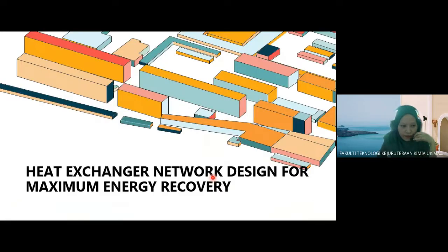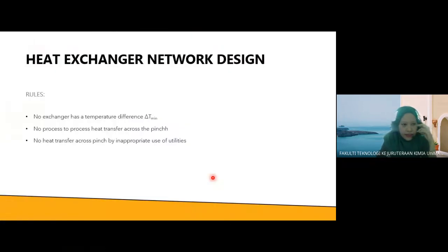Okay, now heat exchanger network design for maximum energy recovery, right? Okay, these are the rules. No exchanger has a temperature difference less than delta T min. Okay,